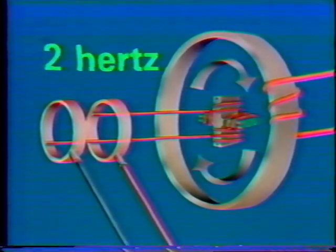Think of it this way. The rotor on a 4-pole generator only needs to make 1/2 of a revolution to complete a cycle. Only one north pole and one south pole need to pass the winding to make one complete cycle. If the rotor in a 4-pole generator makes a complete revolution in 1 second, it will produce 2 hertz. If you look at the generators in the plant, you'll notice that they're all producing 60 hertz, but they may not all be turning at the same speed. This is because they may not all have the same number of poles.